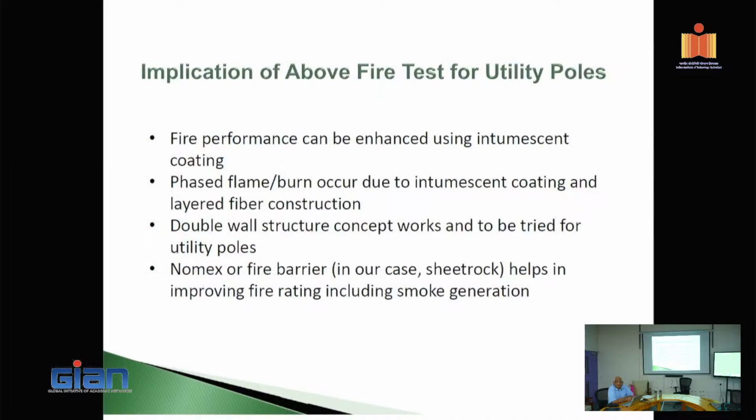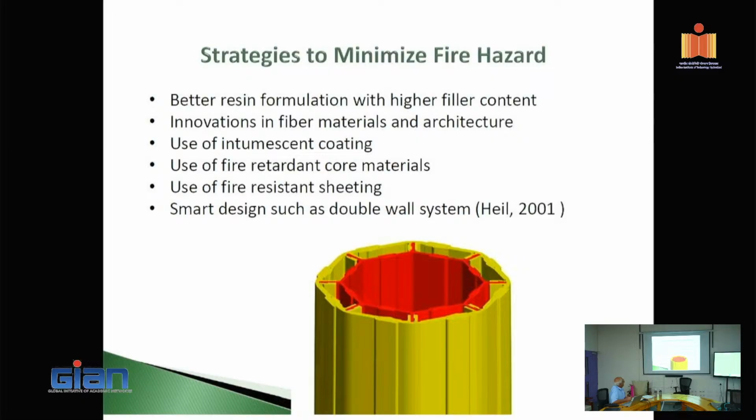Typically, fire ratings are based on a half-hour rating, 1 hour rating, and so on. In a concrete building, the rating depends on the clear cover: a half-inch cover is 15 minutes, 1-inch cover is half an hour, 2-inch cover is 2 hours, things like that. That's what we are talking about. That would tremendously enhance it.